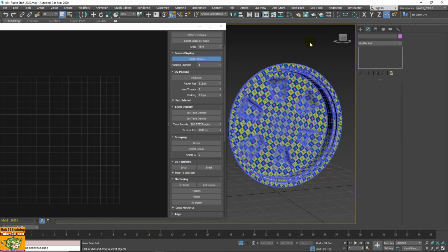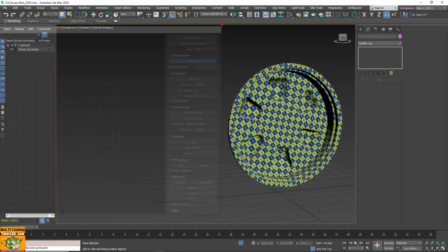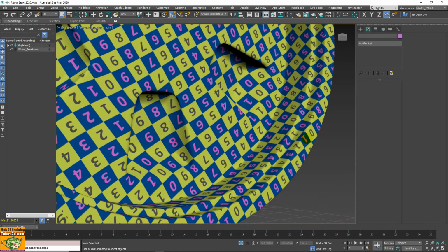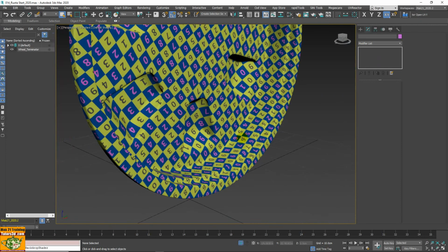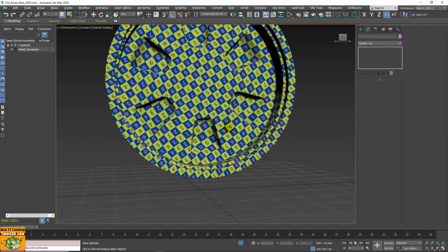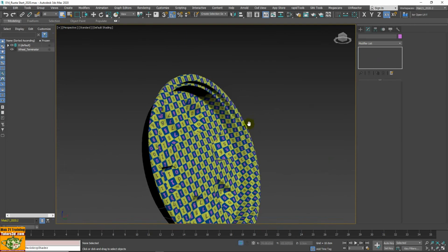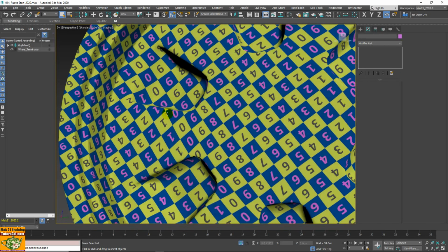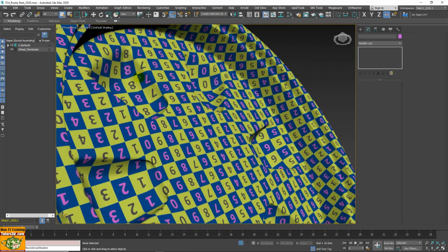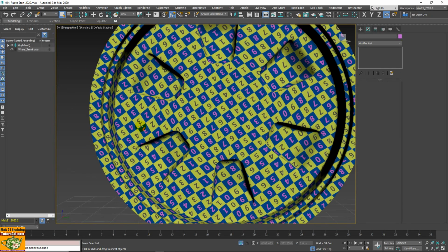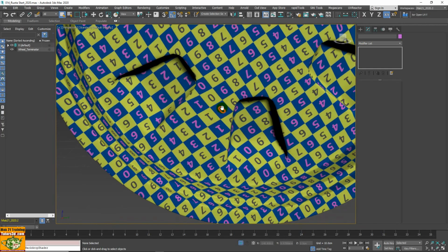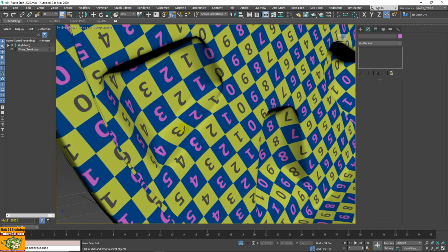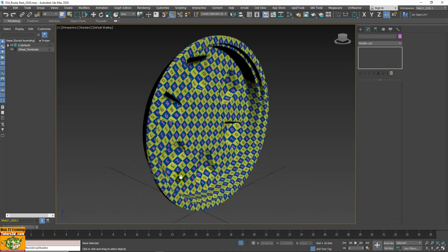of the edge with the F4, and let's go for a moment to see and observe how it solved very well. In practice the distortion that was there because it managed to flatten its mapping coordinates. The interesting thing is that where there are hollows, it relaxes them and manages to relax them without practically creating sides, edges that overlap each other. So it's very smart about this area.